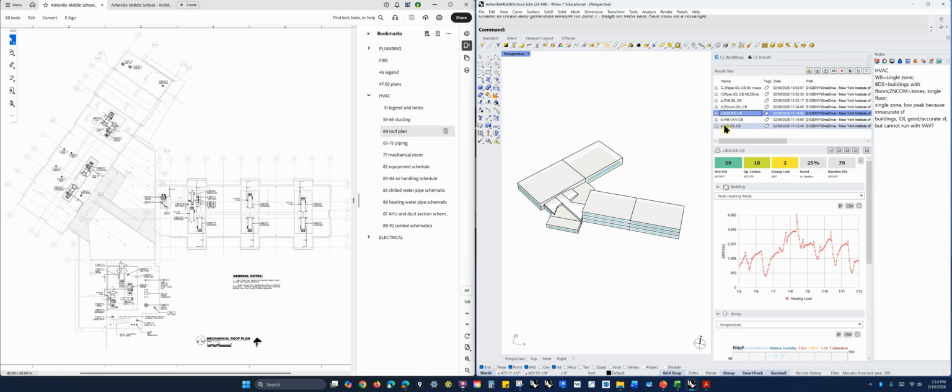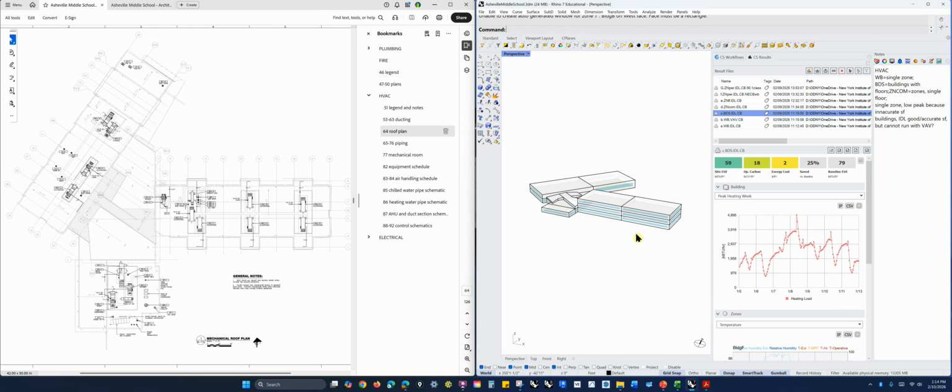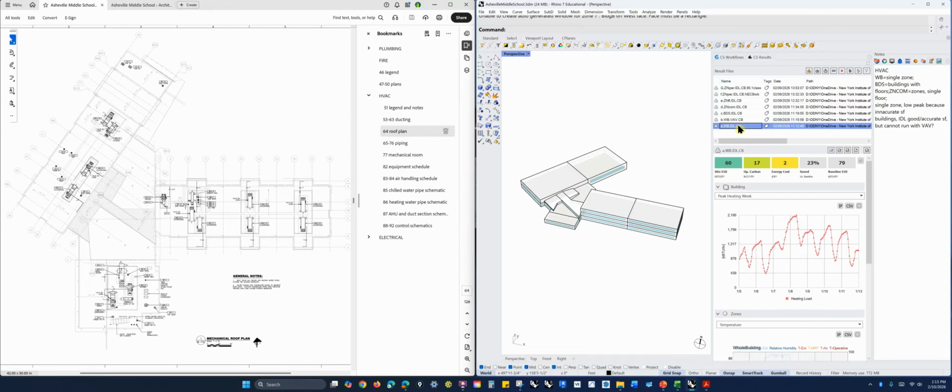But the point is now I have modeled the building with floors. It's the same volume pretty much as the last one, or maybe exactly. I think I might have done this one first and then combined zones to make the other one. I don't remember. But everything else is the same except now, this was the original 2195 for heating load, and in this version I'm at 4895, so much more. I think that the cooling loads are much closer. We could try to surmise why, but actually no, it's 450 and 160.